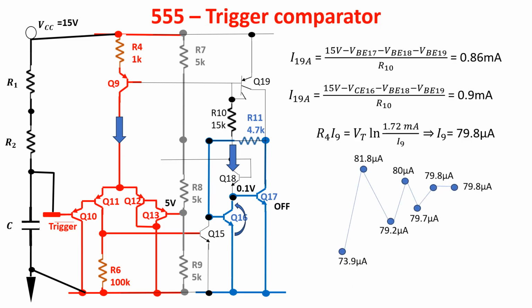When the voltage across the capacitor is below 5 volts, the currents flow in the left branches of the differential pair, so in R6, assuming Q15 off. The voltage in R6 increases, and when it reaches 0.7 volts, Q15 switches on, keeping the voltage on R6 at 0.7 volts. So most of the current goes into the base of Q15, and it has to be enough to force Q15 in saturation mode. If Q15 is in saturation, Q16 is switched off, and the flip-flop changes its state.